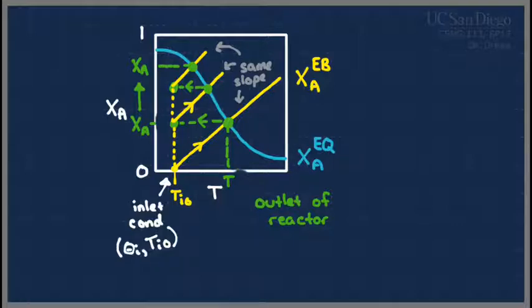How do you get the reactants to stop reacting in the heat exchanger? Yeah. Typically, you remove a catalyst. Or if your inlet temperature is below any appreciable reaction rate, you cool it down to a reasonable temperature, something like that. The most common way, though, is take the catalyst out, and that pretty much stops everything. This is the case for an exothermic reaction.